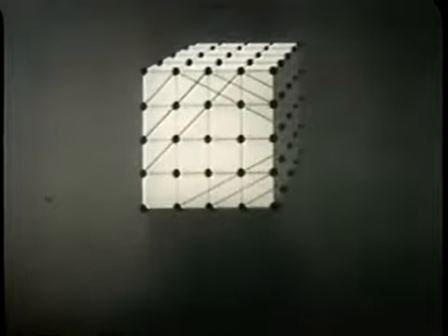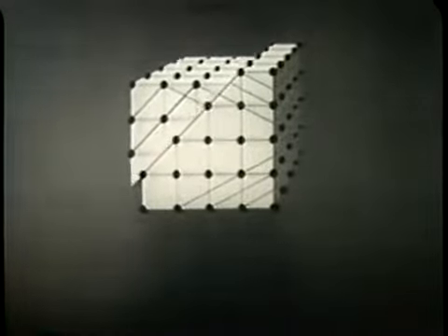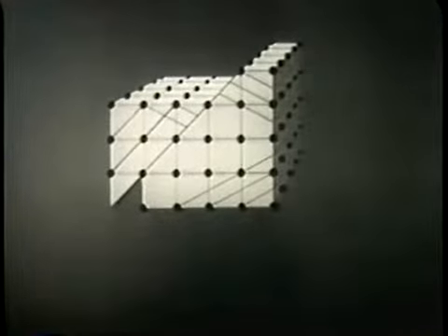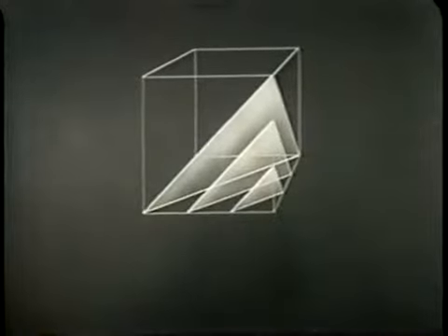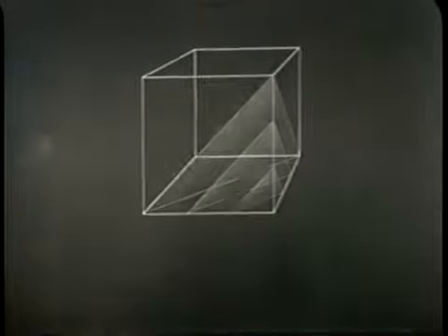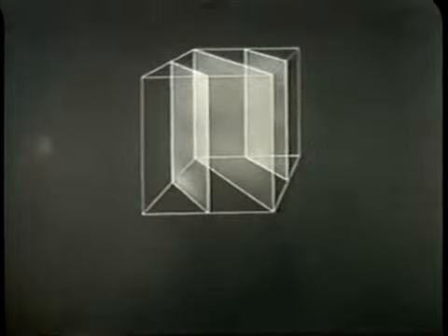It is along these planes of weakness, called slip planes, that the crystal is most likely to glide or slip when deformed. These are important slip planes, along which movement may take place in the aluminum crystal.